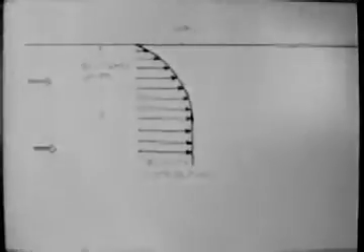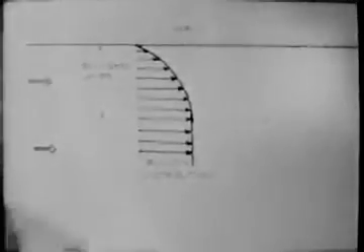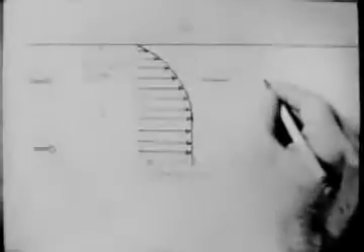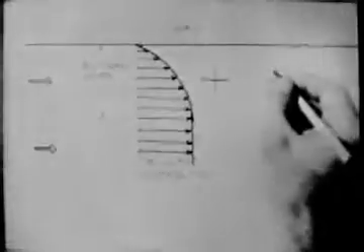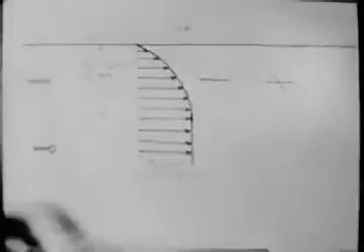Near the wall is a viscous boundary layer, in which the velocity increases with distance from the wall. Let's look at a fluid cross. One leg moves downstream parallel to the wall, while the other leg rotates because of the non-uniform velocity distribution. So there's a net vorticity, and the vorticity meter spins. On the other hand, the flow may be without rotation, even though it is curved.